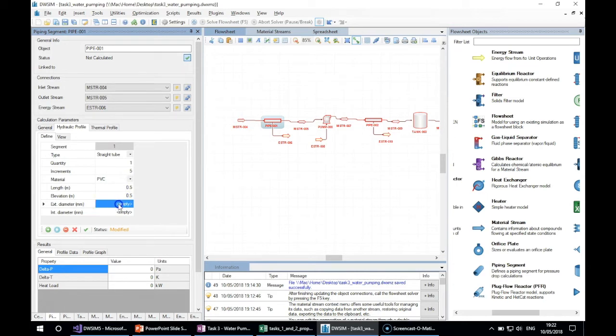And if you double click at this box, you will see a shortcut to input a standard dimension for the pipe, which is this one I've selected, the 1-inch standard schedule 40. Click apply changes to store the profile. And now the next pipe.